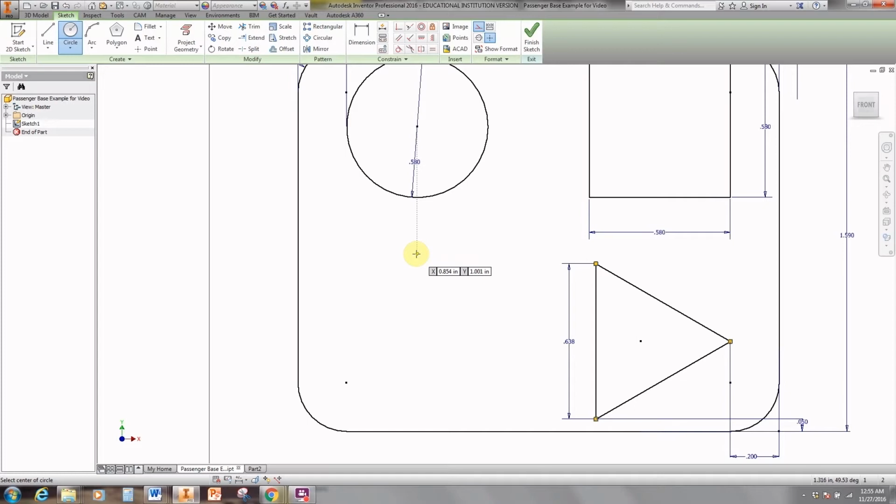So like if I line up right there, it already creates a constraint. That dotted line is showing a constraint there. And I don't want to do that. I want to make sure that this is where it needs to be. We're not going to line it up with any of the other points. So this spot's good. Just pick a spot. It could be this spot, it could be this spot, not that spot, because that dotted line shows up. And I kind of made it show up. I teased it by touching that center of the circle. So we'll choose this spot right here.